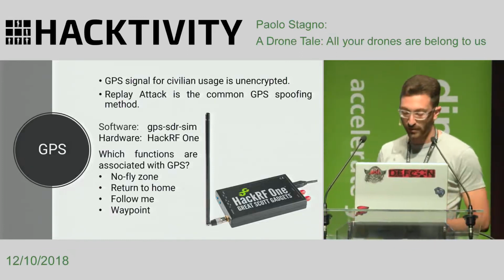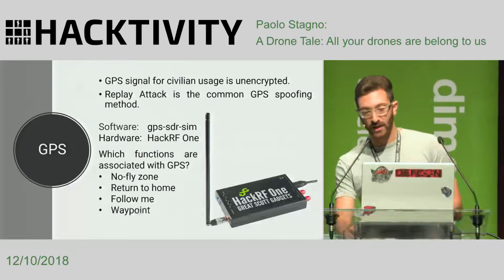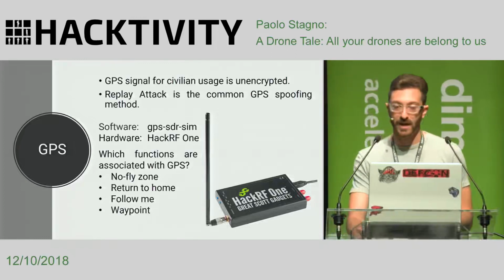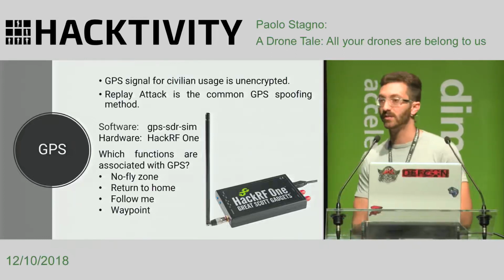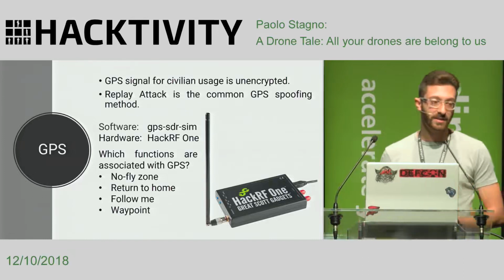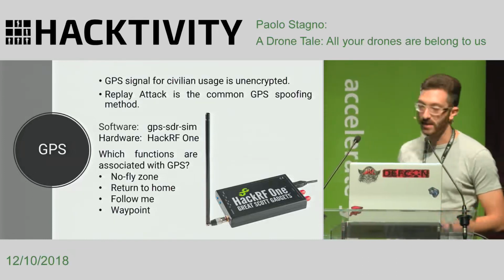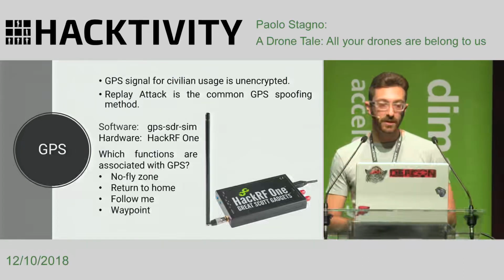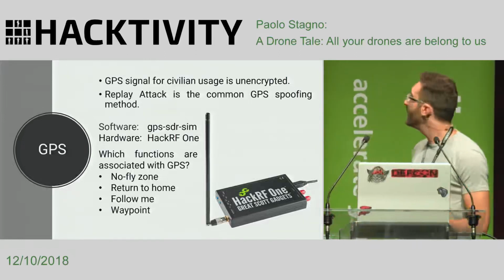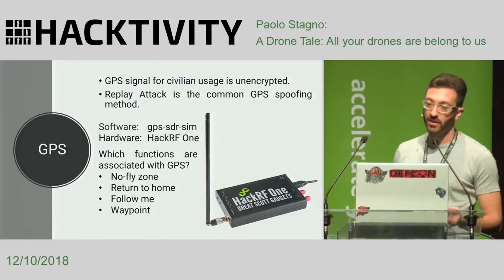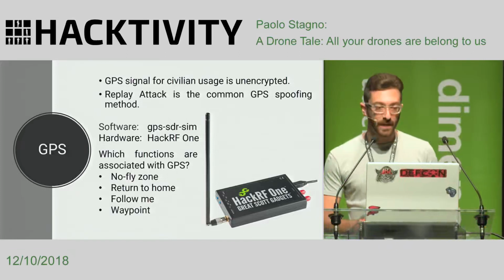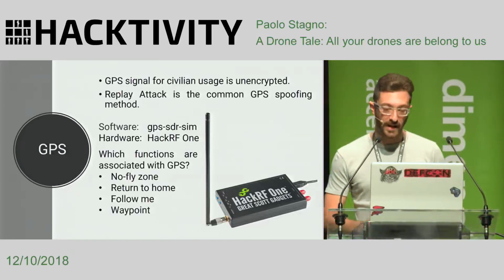It's a great piece of hardware, and it's also kind of cheap if we compare to other devices, because it's 300 euro, but there are other SDR that are a lot more expensive. So the main problem with HackRF is that its internal clock is not precise enough for GPS replaying.